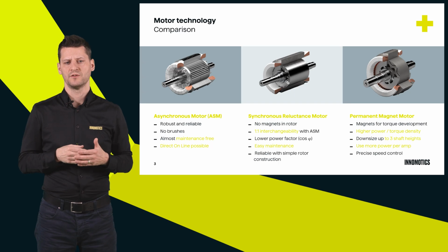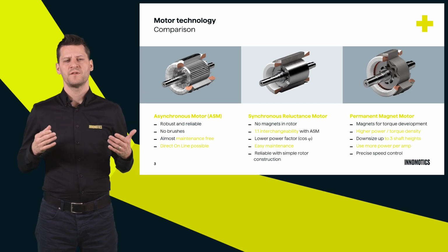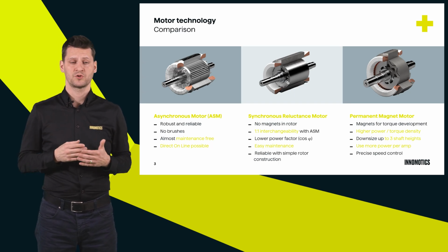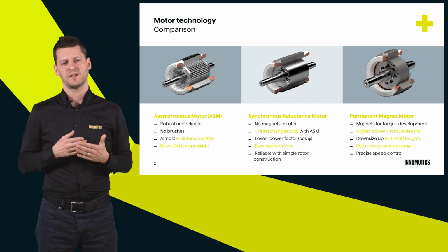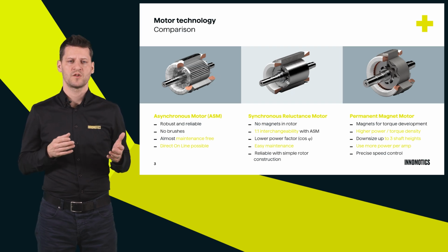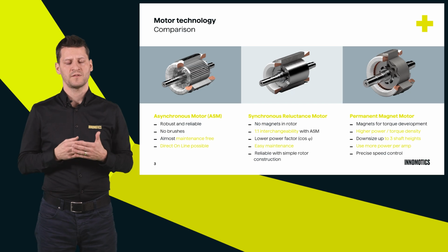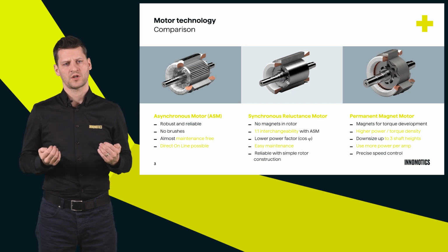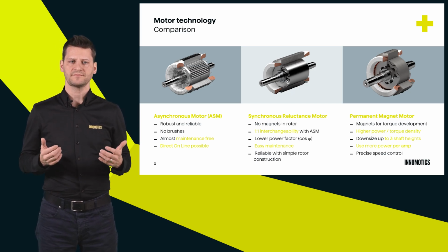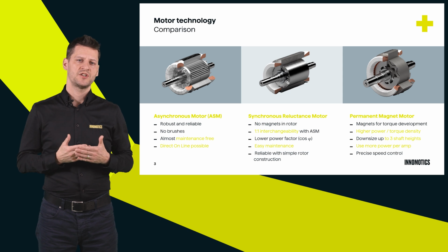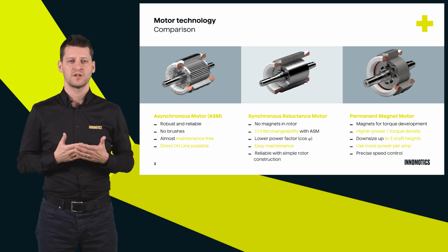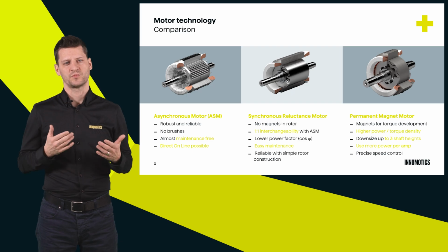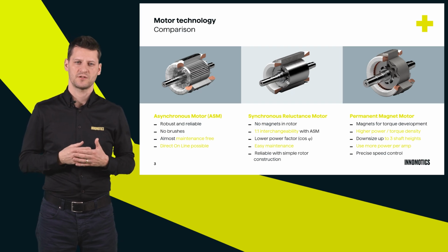We have very high power factor, close to 1, and this enables using permanent magnet motors in one-to-one power matching with the drive and reducing the overall cost of the system. Whenever the application needs that, you can also use this motor without encoder for precise controlling of the application.